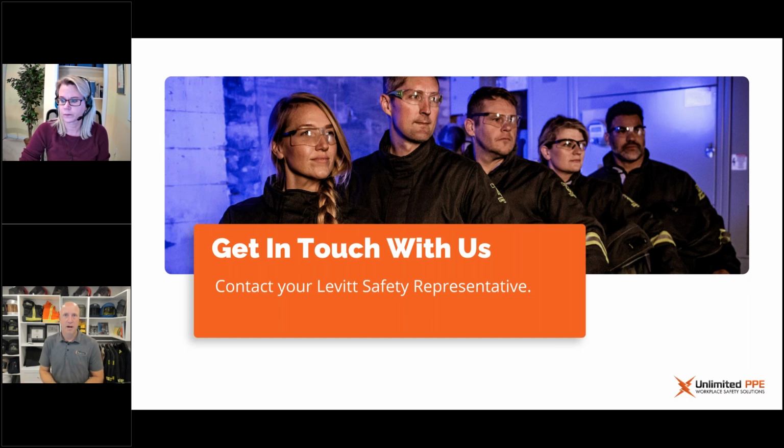Is it possible? I mean, if you're talking about a receptacle on the wall in your house, there's no arc flash hazard. But if you're talking about a voltage level that can sustain an arc across a gap, which then can transform into an arc flash, well, then if you're de-energizing that and you're verifying absence of voltage where you have the potential, when you're using a test instrument, you're touching phase to phase and phase to ground, you need to wear adequate protection. So the process of de-energizing usually requires that arc flash PPE is worn.